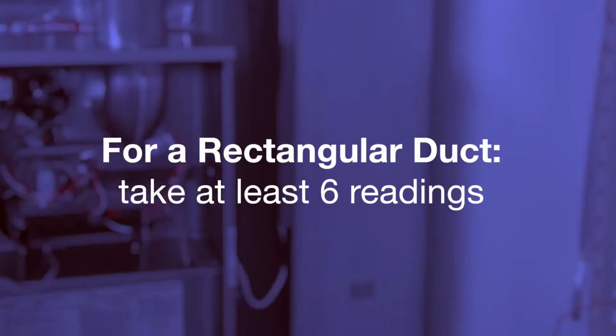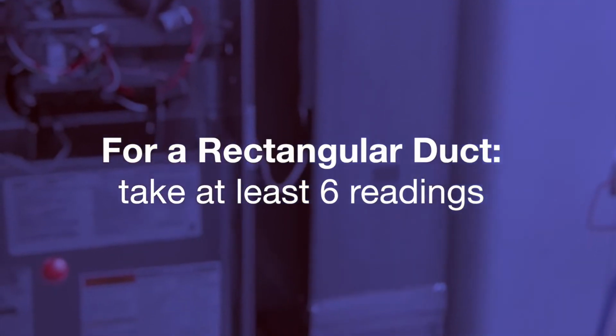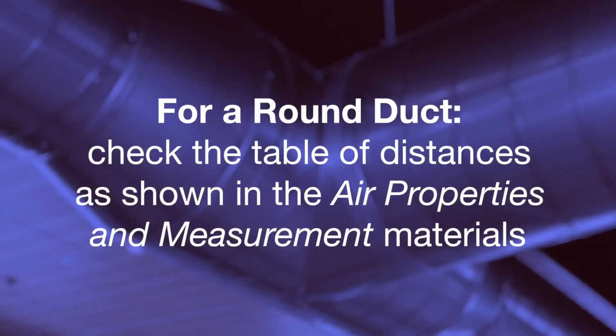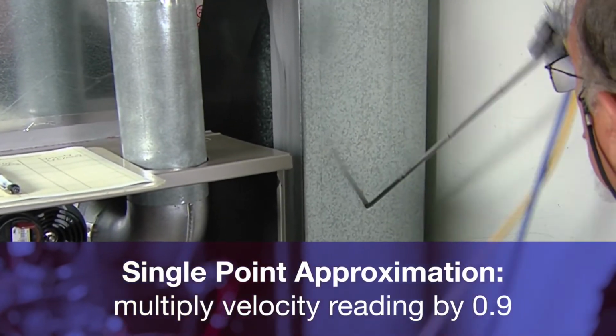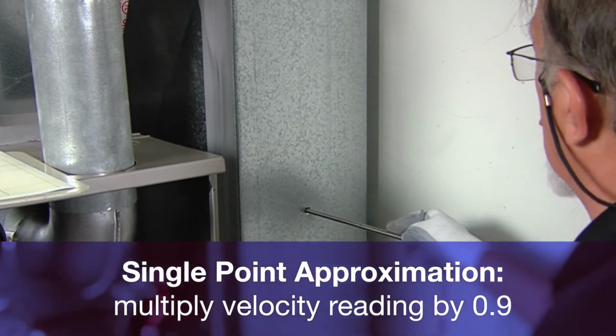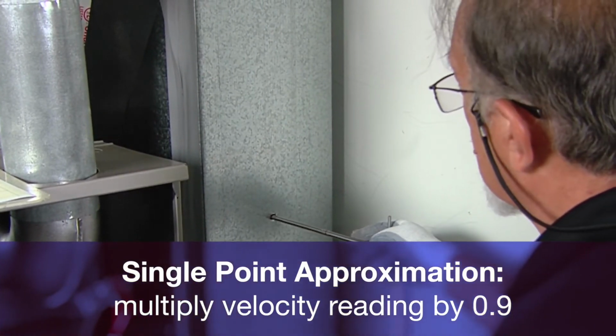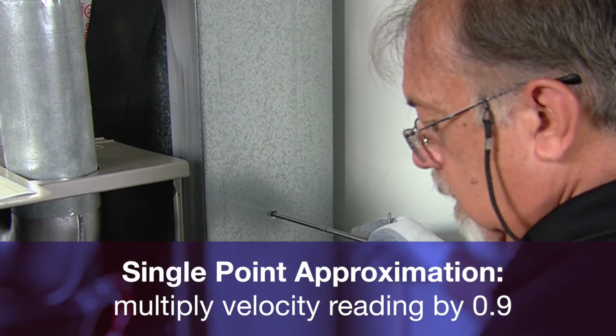Accurate airflow measurement requires the velocity readings to be taken in multiple places in the same cross-sectional area of the duct. This is because the velocity profile in the duct is slightly different in each part of the duct. For a rectangular duct, you should take at least 6 readings. And for round ducts, check the table of distances as shown in the Air Properties and Measurement materials. As a quick test, you can also take one reading in the center of the duct, known as a single point approximation. However, you must multiply the velocity reading by 0.9.